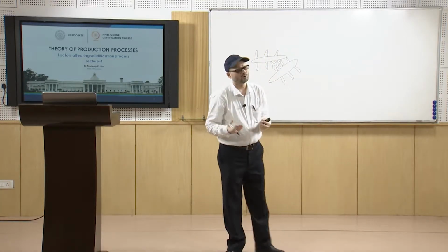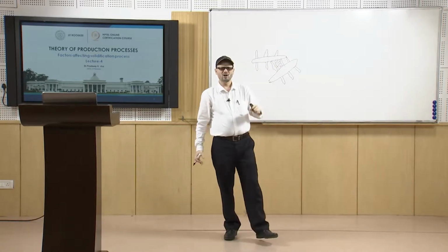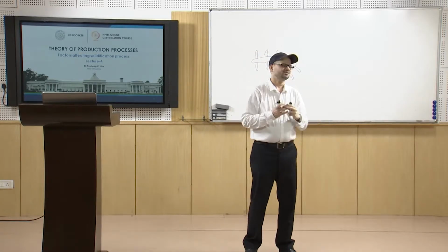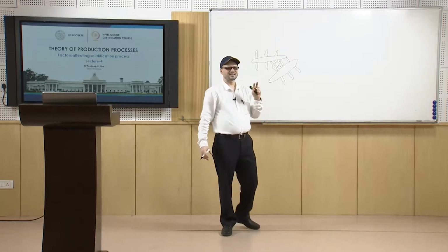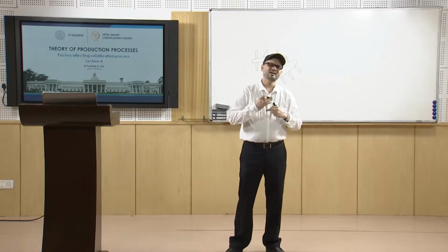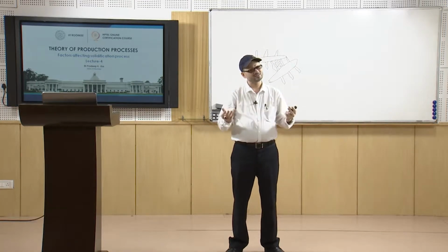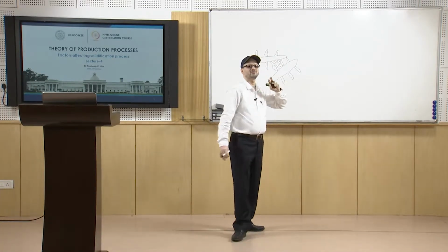Maybe the dendritic arm spacings can be controlled, or the extent of such dendritic formation can be controlled, but it cannot be avoided, because it happens because of the concentration gradient, which is a trait of such alloys.